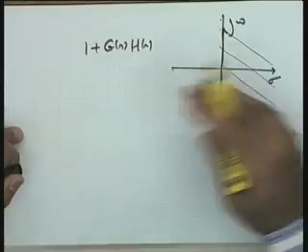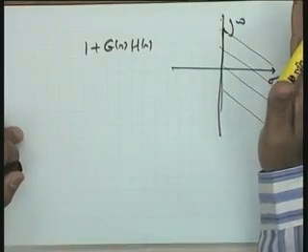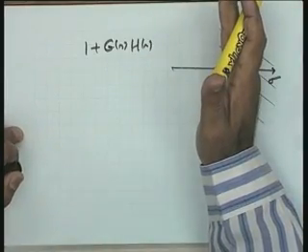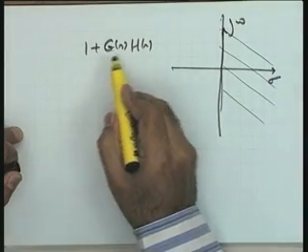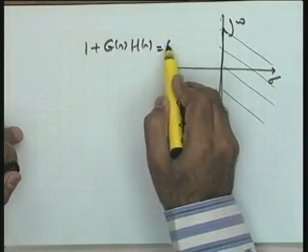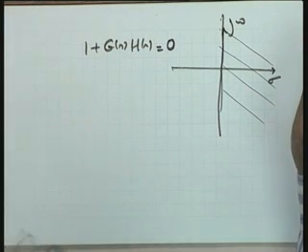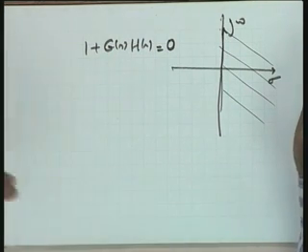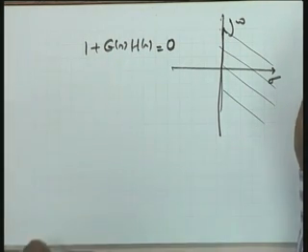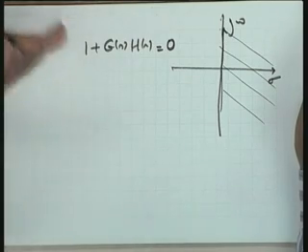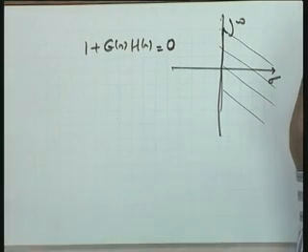If there is no point in the right half of the S plane including the imaginary axis for which 1 plus G(s)H(s) equals 0, in that particular case your closed loop system is a stable system. You see that I am twisting the characteristic equation statement a little because I want to apply this in this way when I come to the Nyquist stability criterion.